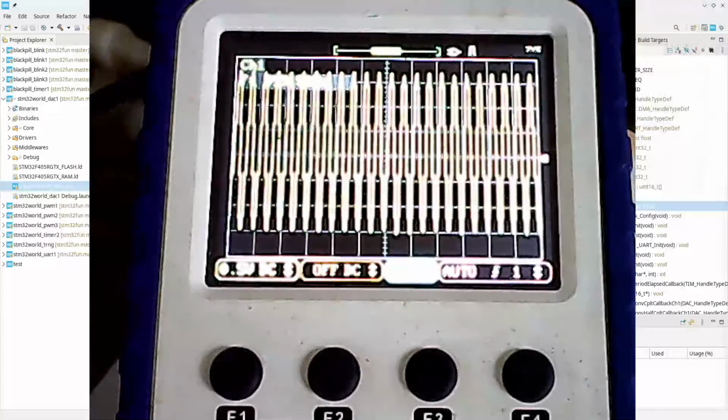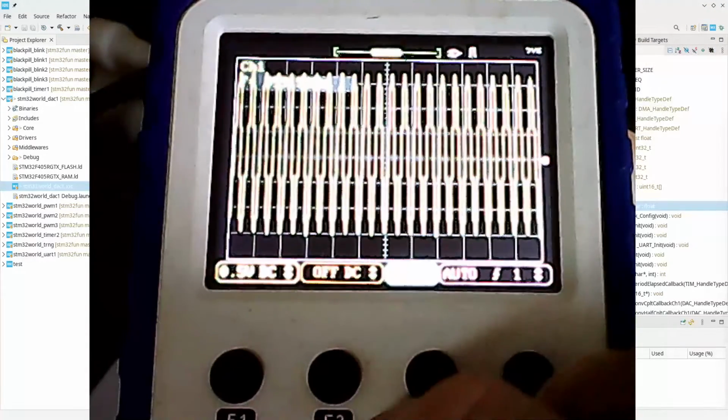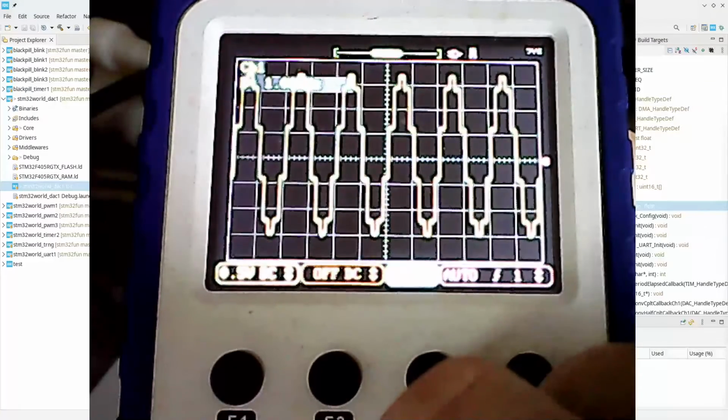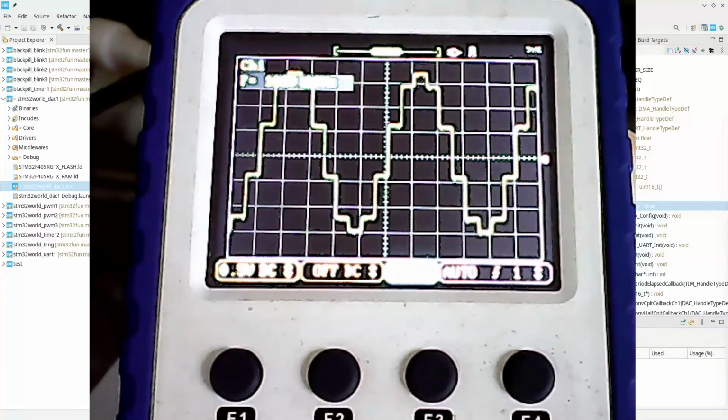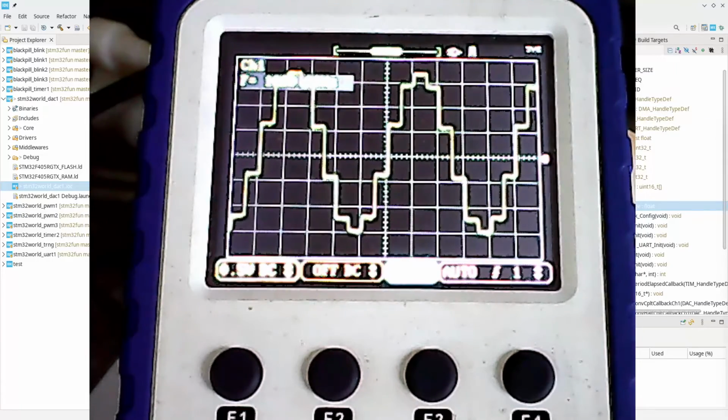device. And you will see I can change the time base a bit here, and you can see it is there. Now you will notice that this doesn't look like a curve anymore, and that is simply because these steps is our sample rate. This is how often we have new samples, so we could try to up that sample rate a bit.